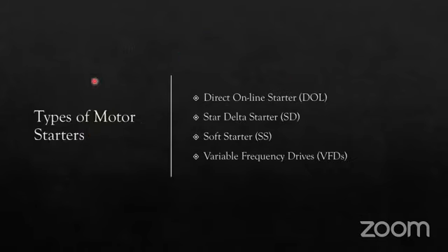So we have already seen this type of motor starter. We have basically 4 types of starters. Direct online starters will be a basic circuit, with supply coming from the MCB, and then it goes to the contactor, and then the contactor will supply the motor. If you need overload protection, you will need to insert the overload relay in between the contactor and motor.